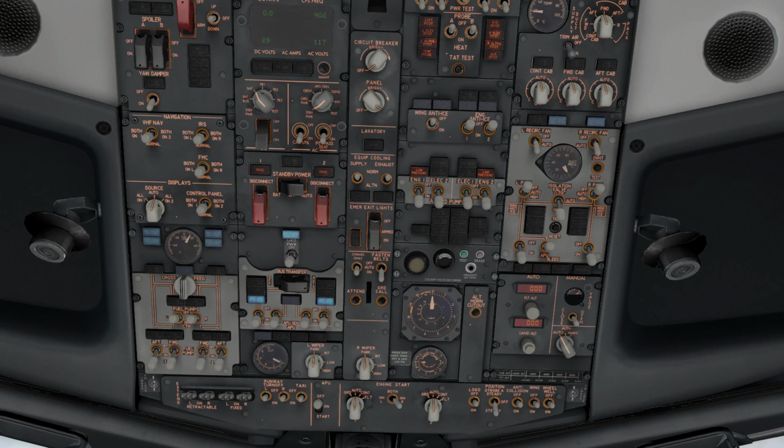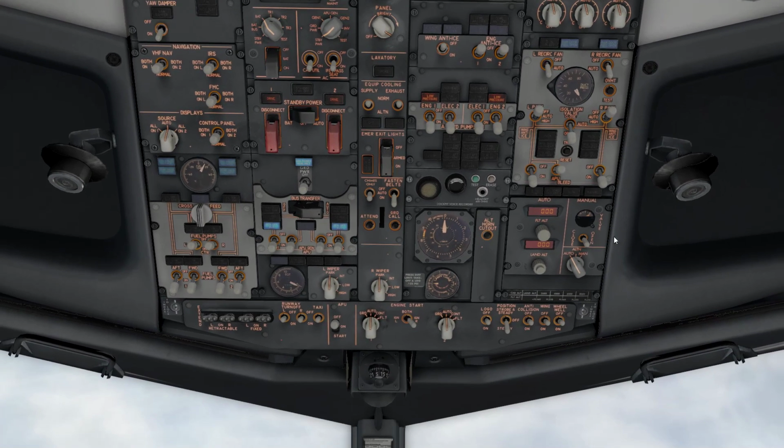startup of the engines. And next below that, we've got two dials, one for flight altitude and another for landing altitude. This is the pressurization setting. I'm just going to pick an arbitrary but somewhat normal cruising altitude for a 737 of 35,000 feet. If you do forget to set this, you're going to start to have problems around the time you climb through breathable atmosphere with the aircraft. So make sure you set the cruise altitude.